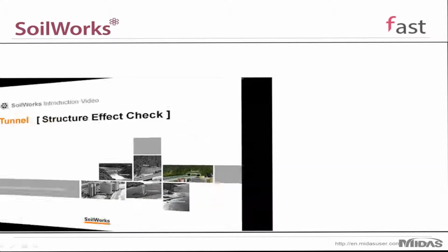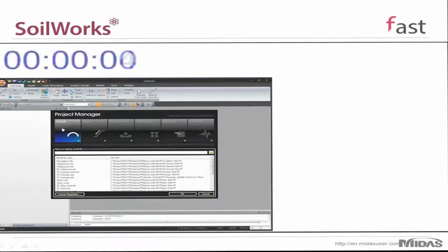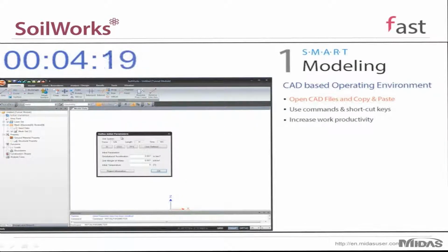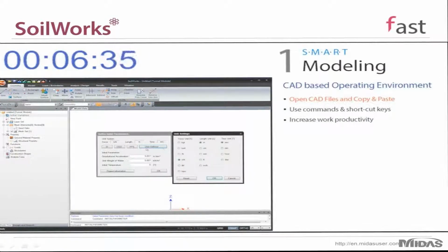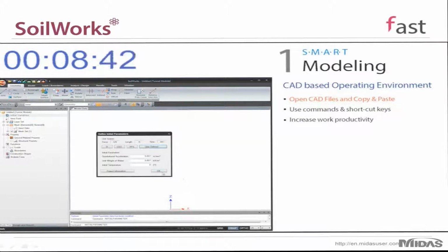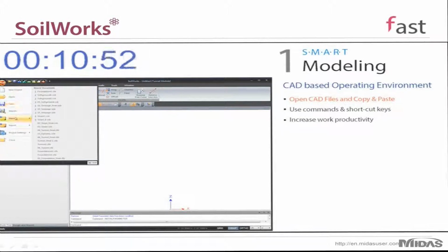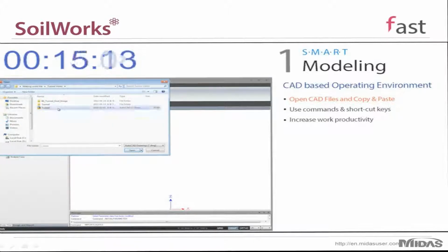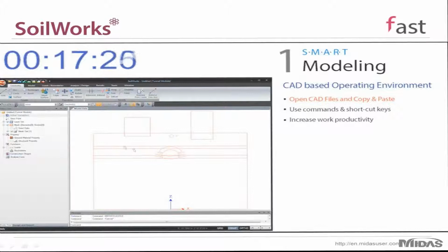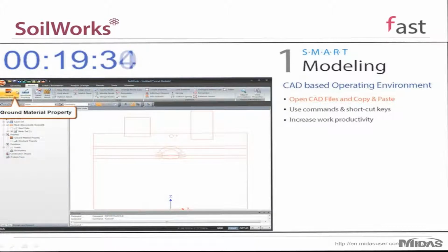Okay. So first, he'll just choose the tunnel module, because obviously this is a tunnel project. Afterwards, he'll define his units. As you can see, we have a broad list of options for your units. Everything's included. Next, he will be importing his AutoCAD file. So instead of having to draw your model on the program, you can just import it directly. So within a few seconds, your drawing is set.